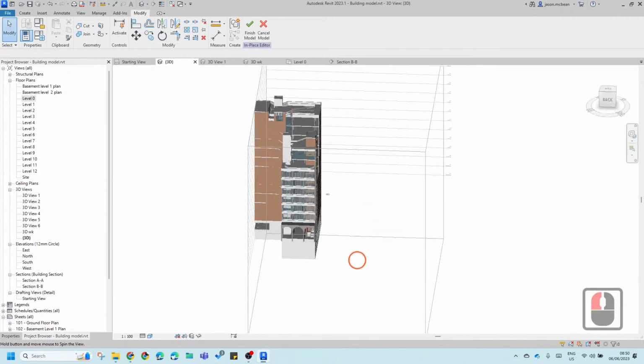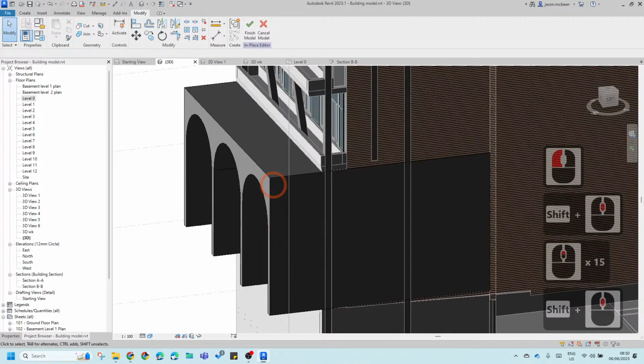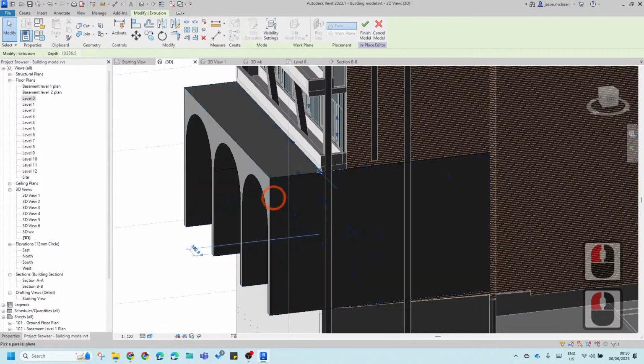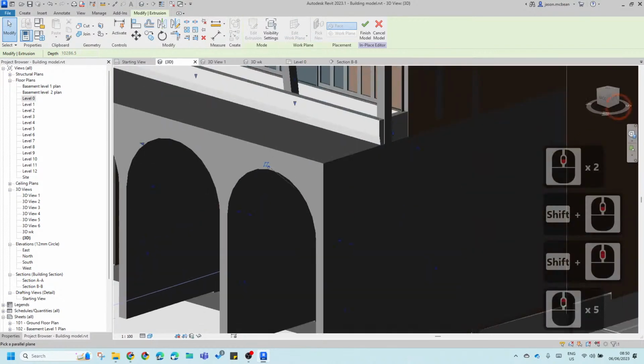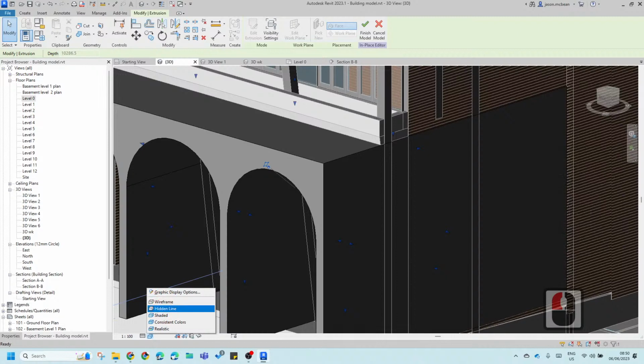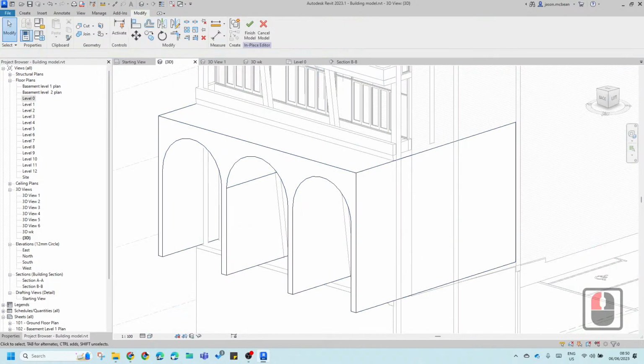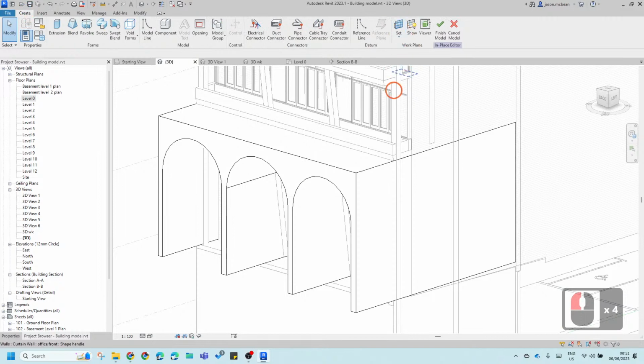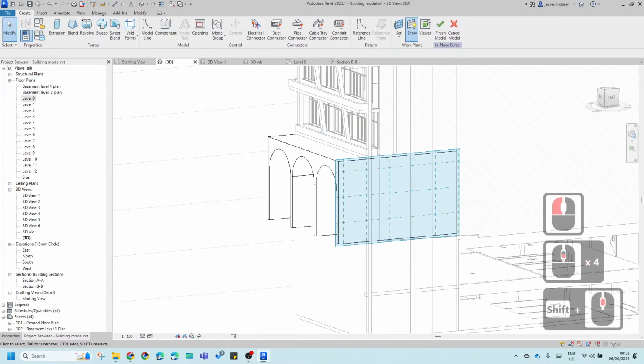So if I go to 3D view, I'm going to use this as a work plane on the side here so I can start cutting away. So I'm going to say edit work plane, pick plane, and I'm going to pick the side of this 3D view. And let's just work like this so we can see. So I'm going to say create, set, pick plane. I want to pick the side of the plane, and if you say show, you know that you're working on that plane there.